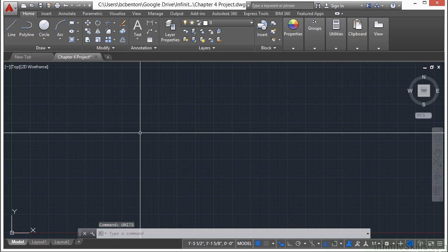Now, as you work on your file, I've mentioned it before, you need to save early and save often. So we've done the save early. Now we've made some changes. Now let's save our file. Press the Control key and the S button on your keyboard. This will execute a quick save. So it just saves the state of your file wherever it is at that moment, and it keeps it. So we have our units set up properly in our saved file. So if something happens to our computer, to AutoCAD, or to anything, it just crashes, which will happen, I haven't lost any of my work.